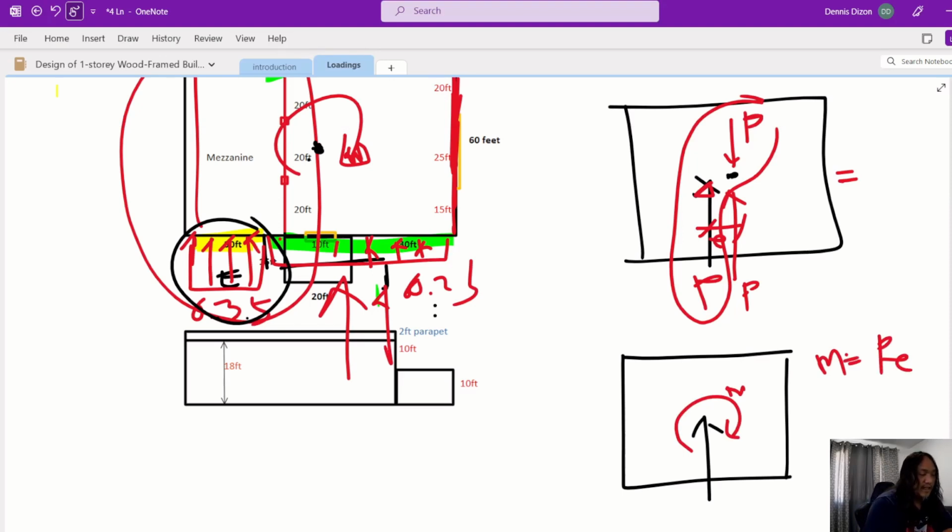For the lateral load alone, you will have a reaction on this wall, which is opposite in direction. But with the addition of the moment load, that clockwise rotation will result in a counterclockwise reaction.